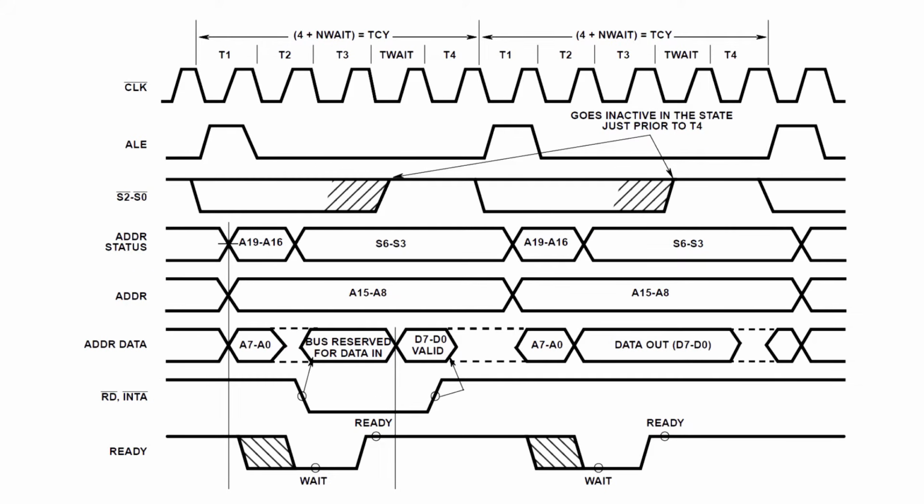Before we go any further, I need to tell you a little bit more about how the 8086 talks to the other devices on the bus. Each data transfer, whether it's reading or writing, lasts 4 clock cycles. To be precise, it may be more than 4 clocks, because the memory or the I/O device may use the ready signal to make the CPU wait a little bit more for the data if it's not ready. But since we shorted the ready pin to its active state permanently, we will never introduce additional wait cycles.